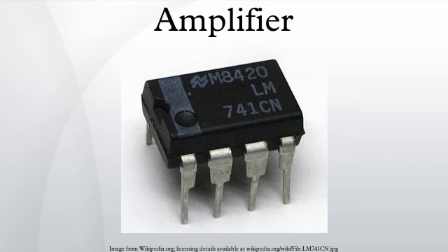The supply voltage is connected to ground via a large capacitor to prevent any RF signals leaking into the supply. The Class E amplifier adds a C between the transistor and ground and uses a defined L1 to connect to the supply voltage. The following description ignores DC, which can be added easily afterwards. The above-mentioned C and L are in effect a parallel LC circuit to ground.